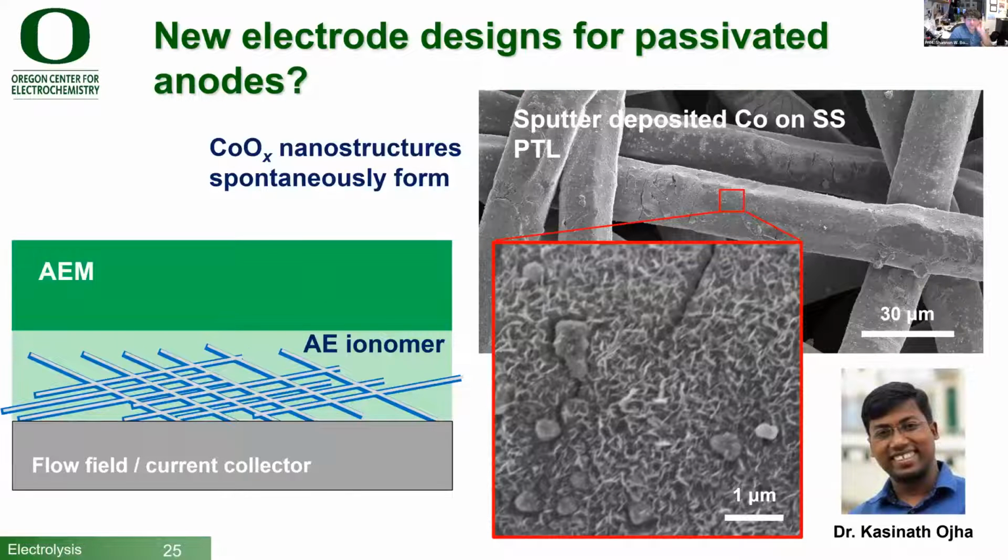So this is an example of what we've been working on. So here's a porous transport layer. Here's some cobalt oxide catalysts. We actually have some much nicer catalysts now. I should update this. But essentially, we've started building catalysts directly on the fiber. So this is a stainless steel fiber in this direction, and then it's been treated to grow some cobalt oxide nanostructure on it. And you can change this nanostructure and change the loading. There's a lot you can do, but the idea is that we could take this nanostructure and then coat it uniformly with this hafnium dioxide or other things to passivate it.